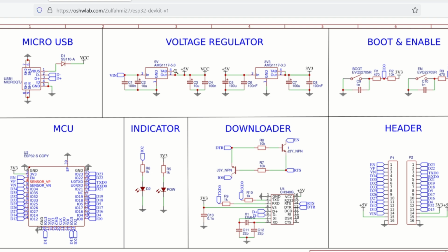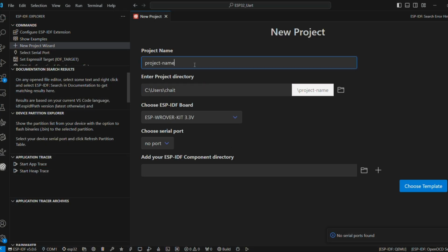Then we have the most important chip, CH340G. This one is a USB to TTL converter, and the TXD0 and RXD0 pins of the MCU are connected to this chip, and D+, D- is also connected to this chip. Thereby these particular UART pins are responsible for uploading the code to the MCU chip. We won't be using that UART, we will be using another one. ESP32 has up to 3 hardware UARTs available, and we'll be using UART number 1.